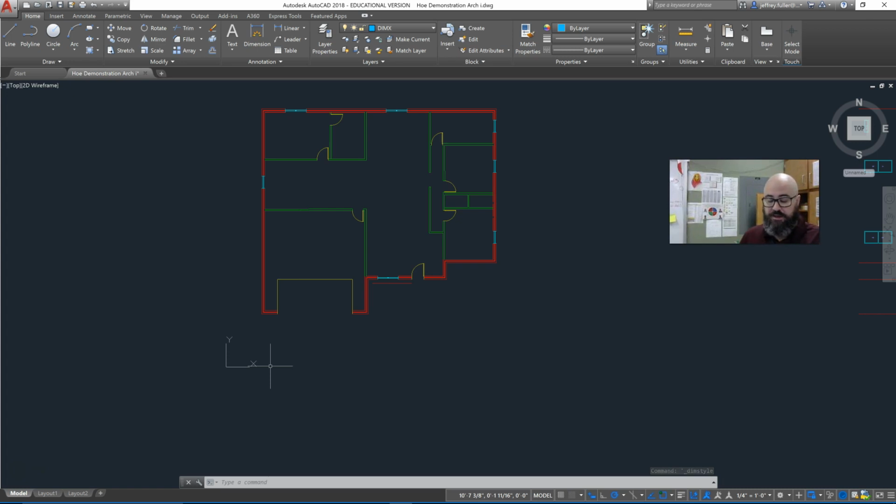All right, now dimensioning your floor plan. When we dimension by hand, with pencil and paper, we set a distance for that very first line away from your house. Now remember, there are 3 lines of dimensions there. That very first line, the one that's closest to the house, is your doors and windows. The second line right after that is your major walls, which means any breaks or any walls that come in contact with the exterior walls.